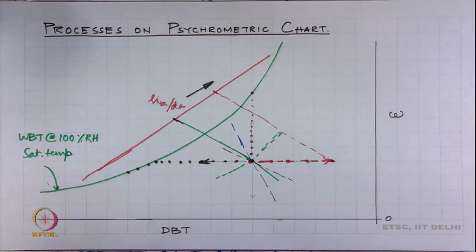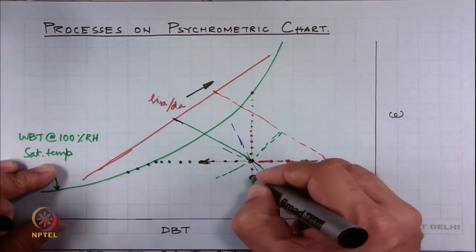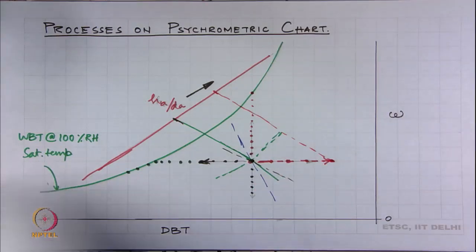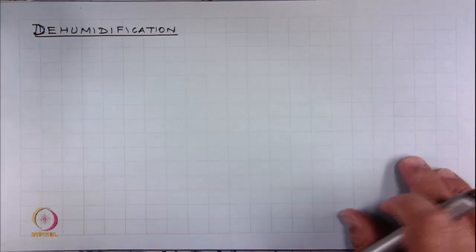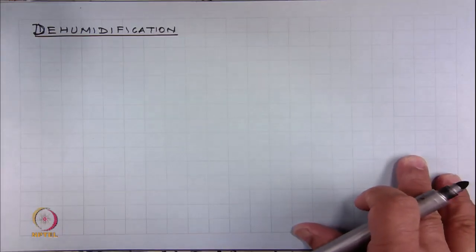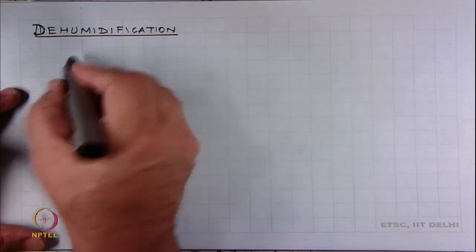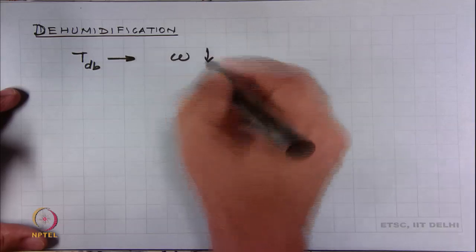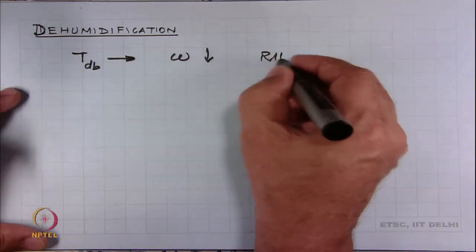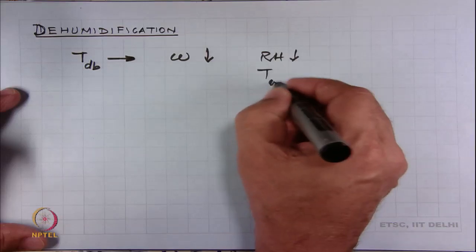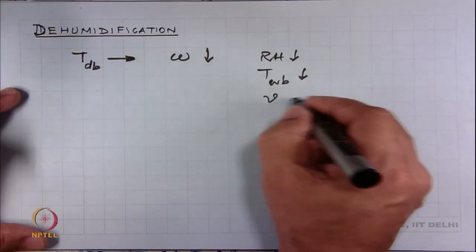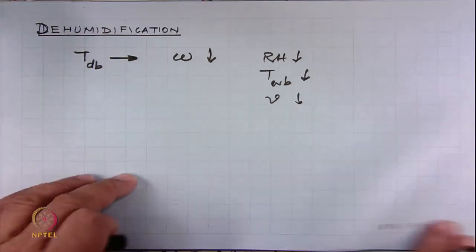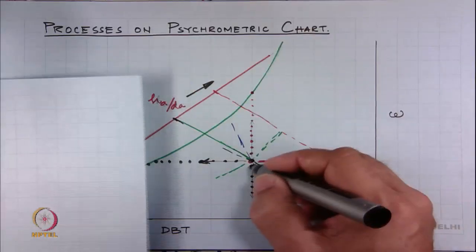The opposite of this are a series of states going down here, which is dehumidification. So, we have a dehumidifier, something that absorbs the moisture, gets the air out, and that is what we are doing there. Again, here T_dB remains constant while omega is decreasing, and with omega decreasing, our H is coming down, wet bulb temperature is coming down, the air is becoming more dense. So, that is these types of processes.